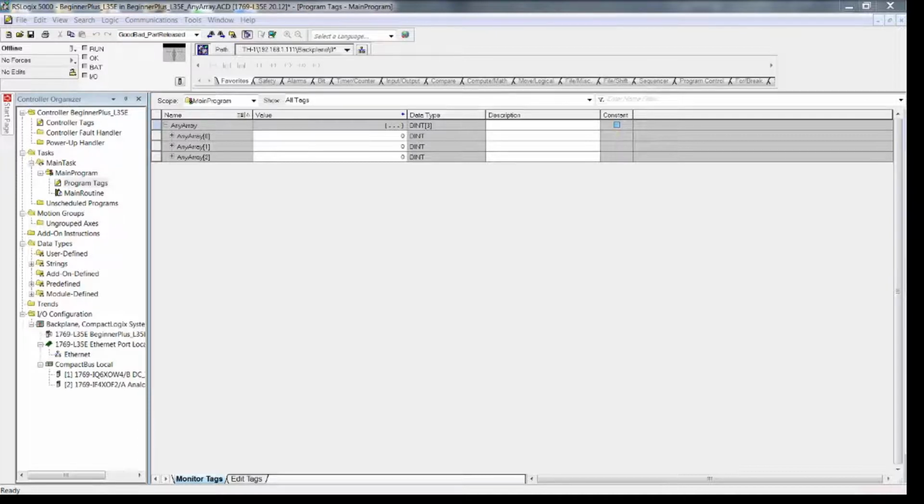We say bit space. Another approach is a linear array, a row of DINTs. When the bits shift left, the most significant bit value moves to the least significant bit position of the next highest DINT of the array.